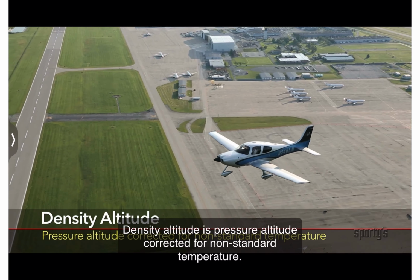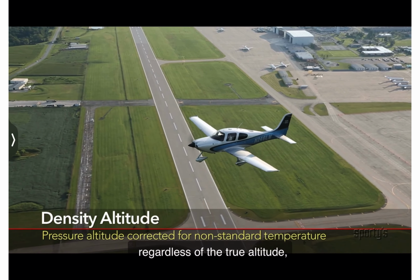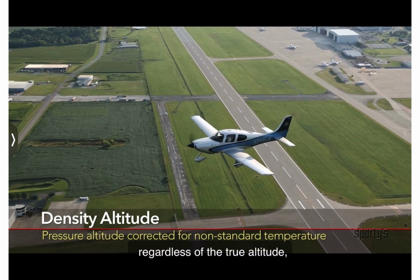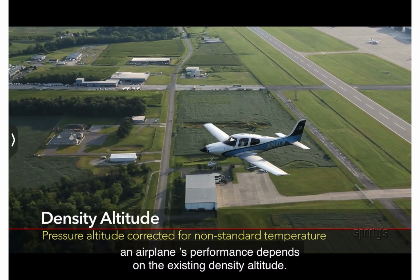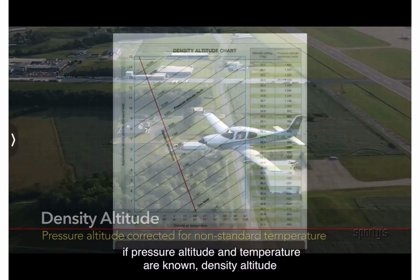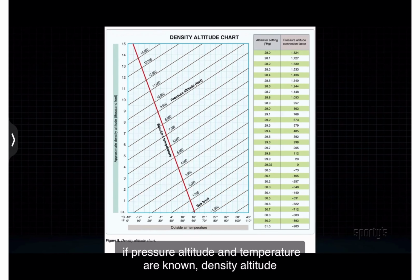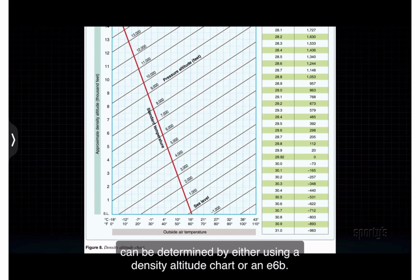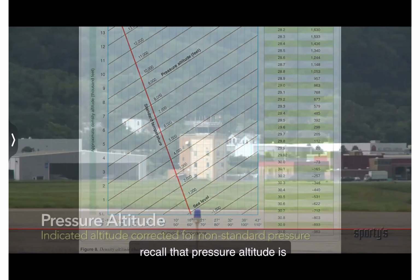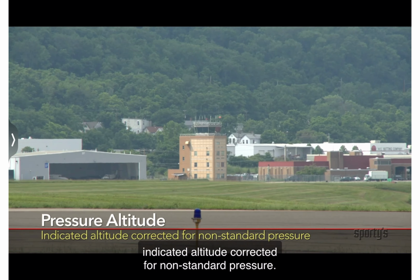Density altitude is pressure altitude corrected for non-standard temperature. Regardless of the true altitude, an airplane's performance depends on the existing density altitude. If pressure altitude and temperature are known, density altitude can be determined by either using a density altitude chart or an E6B. Recall that pressure altitude is indicated altitude corrected for non-standard pressure.